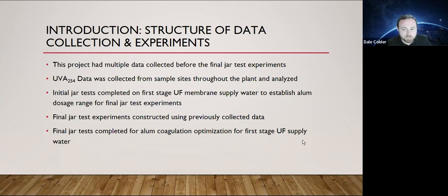After approximately 90 days of UVA 254 data collection, the laboratory staff completed a series of jar tests using the first stage ultrafiltration membrane supply water to establish a dosage range where alum could be used to target the removal of organics. And that data was used to establish the final set of jar testing experiments.